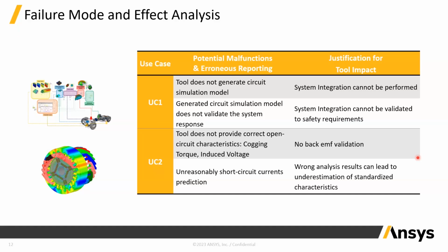For the sake of an example, assume that you have a design in the Maxwell environment and you want to export an equivalent circuit or a corresponding reduced order model from a 2D or a 3D simulation into the circuit simulation for further validation. One potential malfunction, once you define the design, is that the tool, in this case ANSYS Maxwell, does not generate the circuit simulation model.